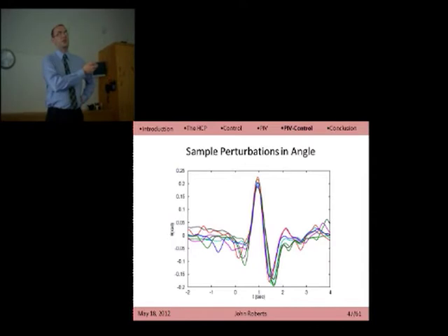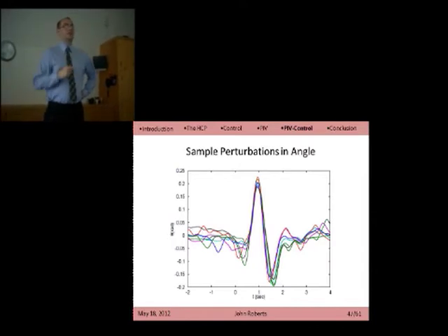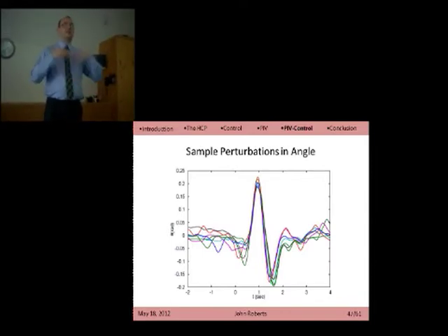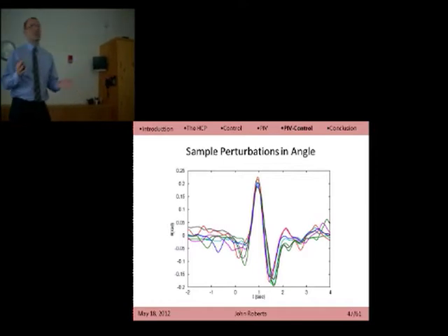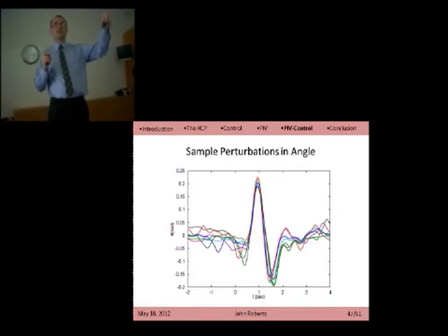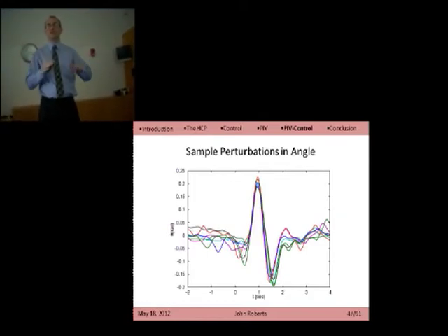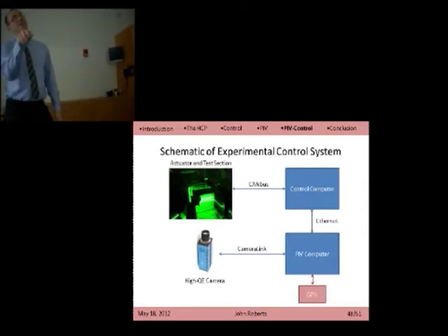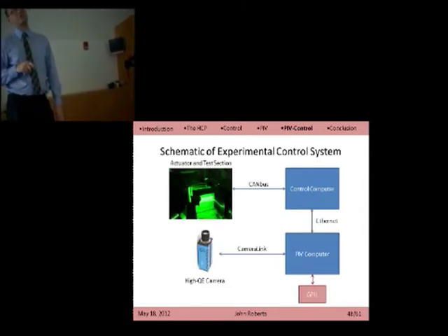We have a bunch of trajectories of the system getting hit by vortices. We again fit a local linear model around the measured data, and we say, okay, how do we compensate for the perturbation in this model? How do we design a controller which, when it sees that vortex ahead of you, starts executing a controller that will minimize this deviation, using the sort of local understanding of how that vortex affects us? If we do that design, we now have our sort of full control system in place.